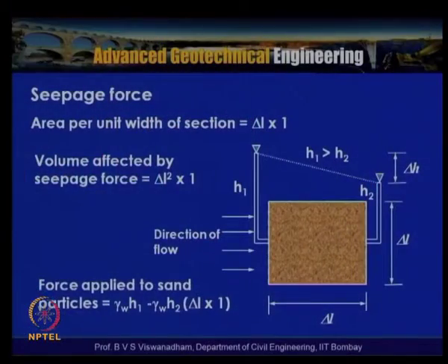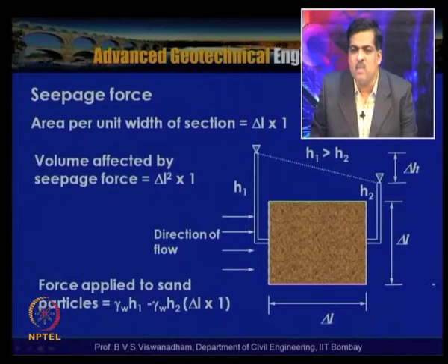Both the seepage force and seepage pressure act in the direction of the flow. The seepage force can also be obtained by this particular deduction. For this, consider a rectangular element with dimensions in 2 dimensions, delta L in this direction and delta L in this direction, and assume that this is the direction of the flow, because here the pressure head maintained is H1 and here the pressure head is maintained H2.